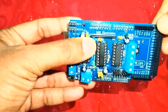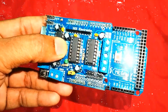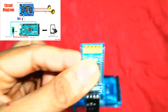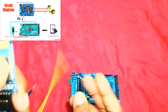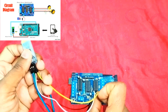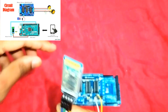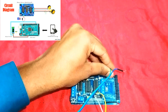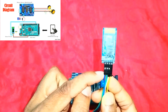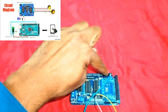This is why we cannot use Arduino Uno here, and why we have used Mega, which has extra TX and RX pins for serial communication. So take the Bluetooth module and connect the connectors. Here the yellow wire is the VCC, positive 5 volt, so connect it with the positive 5 volt line and connect the ground with the ground line. As you can see, green is the TX, so connect the green in the RX point of the Arduino Mega. The last connection, the blue wire, is the RX pin of the Bluetooth module, so connect it with the TX pin of Arduino Mega.